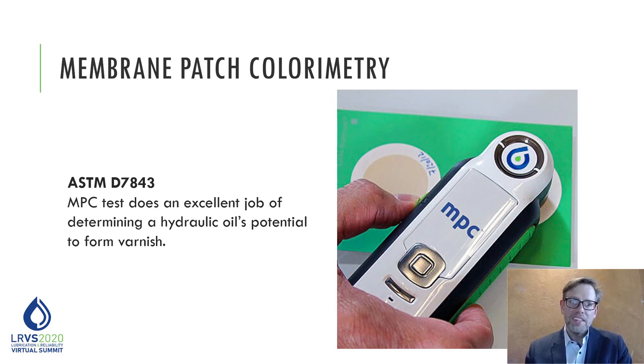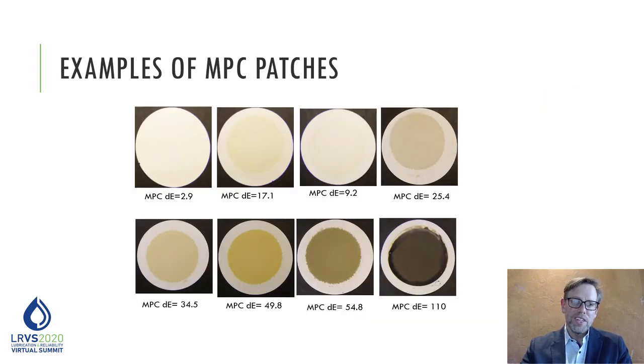And if you look at the ASTM D7843 method, the first thing you will notice is that it's actually a standard that's created for turbine oil. And although that is true, the genesis of this test was a colorimetric test that was developed by Dr. Sasaki in Japan, where literally he has tested this in over 10,000 different hydraulic oils. So the genesis of the MPC test, in fact, has been used very successfully in hydraulic oils for years, and certainly is very, very relevant.